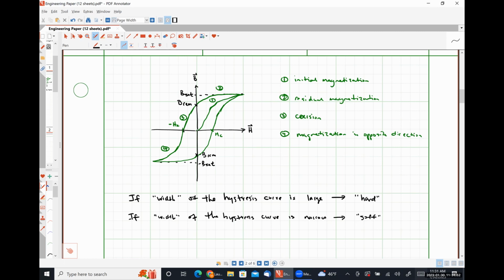Soft magnetic materials are what are used in transformers and induction motors, because we know we are going to have these things hooked up to the sinusoidally varying current. And so we want the magnetization to switch back and forth very easily so that we don't incur a lot of losses in that electromechanical transduction. Right.